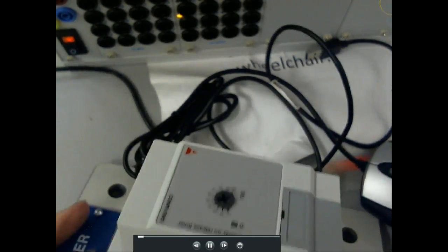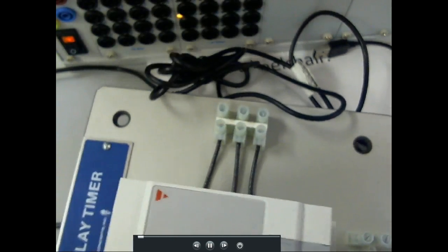Now more and more what we're moving to is solid state timers. Now what advantage does solid state, which means electronics, have over those mechanical timers like that? Yeah, no moving parts. So that guy we can fail 2 different ways. We can fail electronically or electrically, or we can fail mechanically, right? This guy can only fail one way. So this is an off delay timer. All I do is set the time, I just turn a little knob right here.